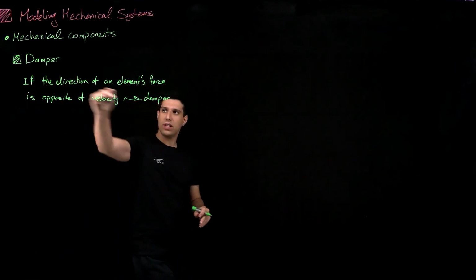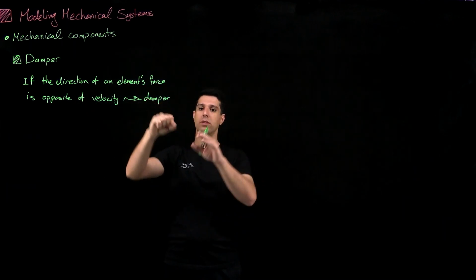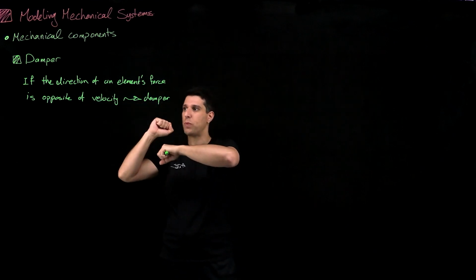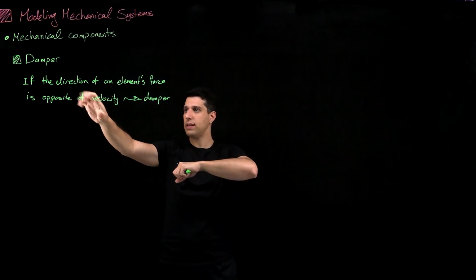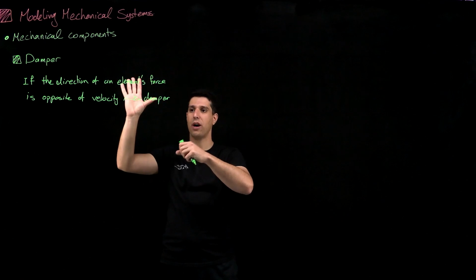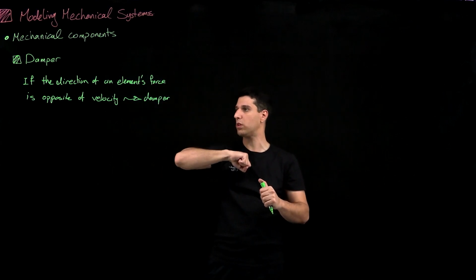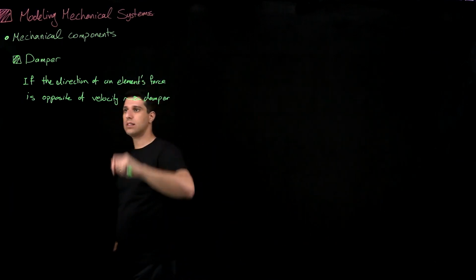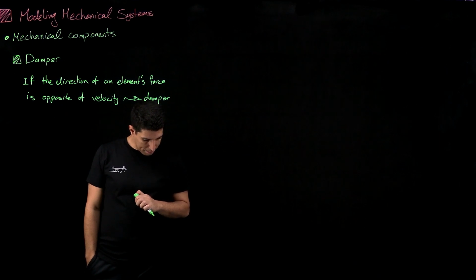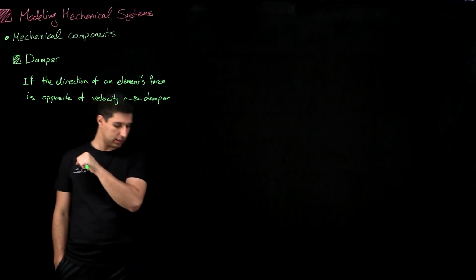The reason you can think of it is simple. If the force is always in the opposite direction of velocity, so I'm going this way, and I'm always pulling it back wherever it's going, I always pull back. I'll get into this a bit later, but the displacement times force, F dot dr, is always going to be negative. So that element always does negative work, and it turns that work into heat often. So this kind of element always takes energy out of the system.